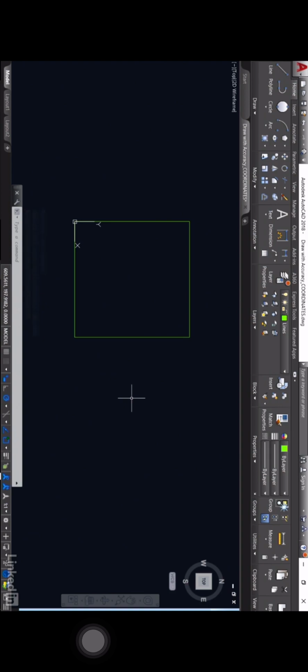So as you can see, using that relative @ with my coordinates allows me to draw really accurately in AutoCAD. Now, remember, object snap tracking, object snaps, and polar tracking. We looked at those in the last video. What we're going to do is utilize those a little bit to create a point where we want to draw from. I'm going to go to the line command again on the draw panel. I'm going to hover on that midpoint snap there, and hover on that midpoint snap there. As I come down, that'll give me the exact center point of the square, and I click.